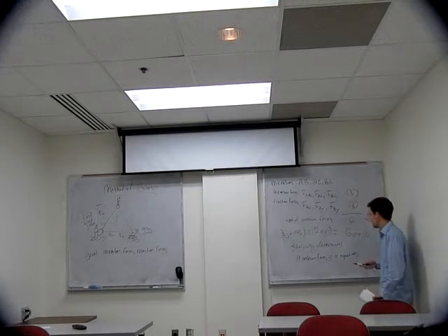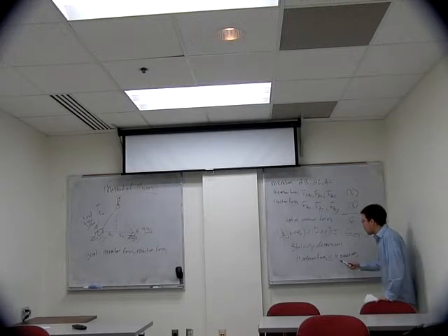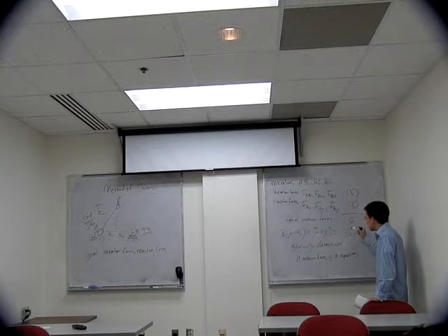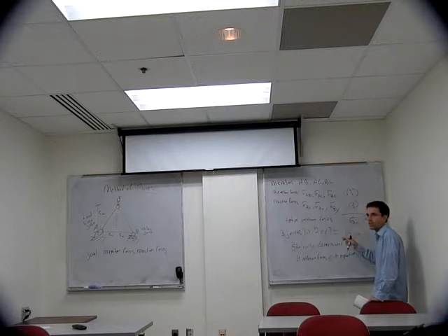So that is less than or equal to? Or does that matter? Right. We have the case where it's equal to, but if we only had 5 unknown forces and we could generate 6 equations, we would still be able to determine what all 5 of these forces are. So that's fine. So this would be like an overdefined system. So will there be a solution that can satisfy all the equations? Yes.